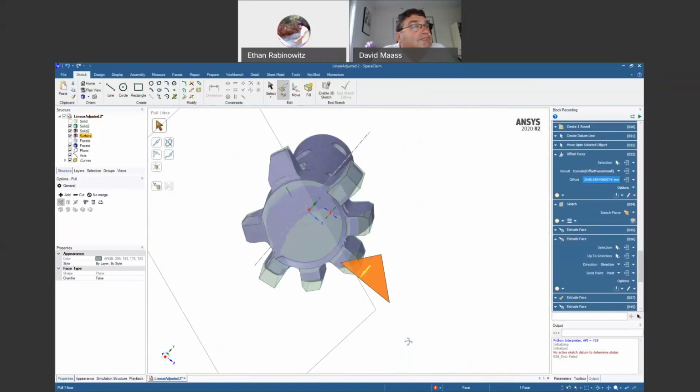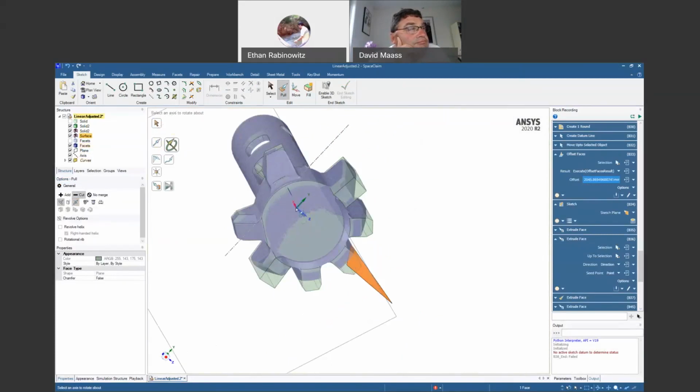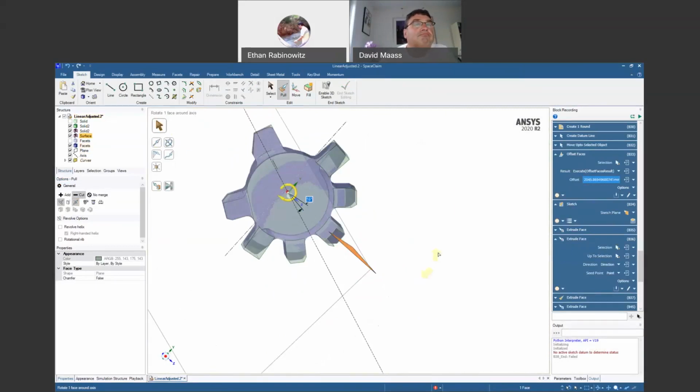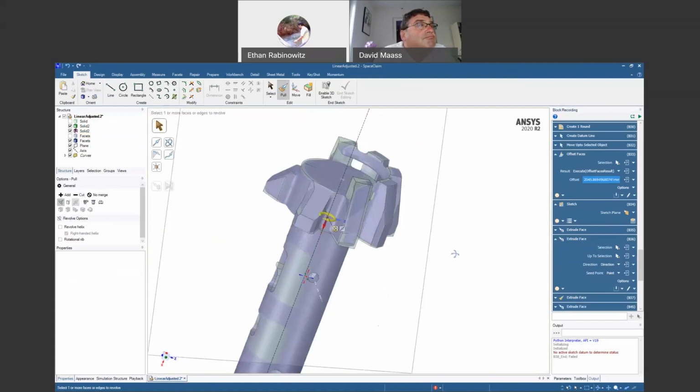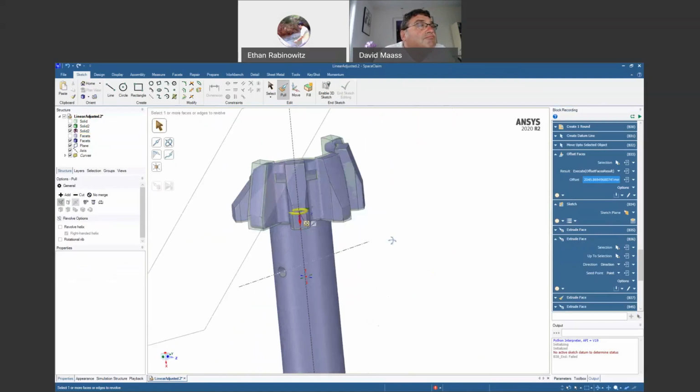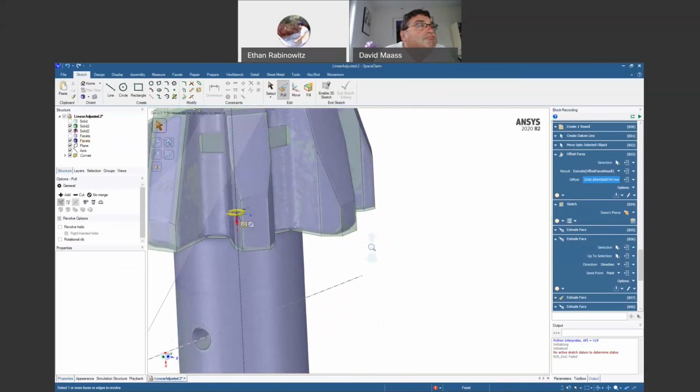And actually, I sketched it in the middle and I don't want it to go all the way around. So I'll turn on both sides, my cut, set it up as a revolve around X. And here I'm actually going to drag so that I can stop it when it gets to these and doesn't further cut. So that is the majority of those parts.